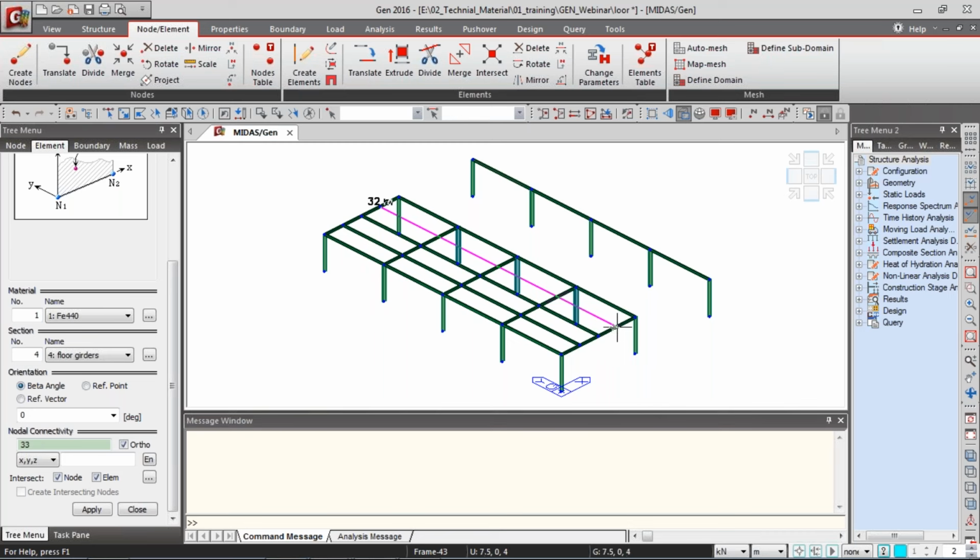So this becomes easier. Okay, now let me show some more snapping tools for making wind braces. Now let's choose wind braces. So let's turn off the ortho. Now we are snapping over here, as you can see, in the center of a beam element. So we do not need to select that element and divide it into two and then create the elements. Instead, you can just directly click on one node and click on the other center, and it is snapped, so it automatically creates a node.